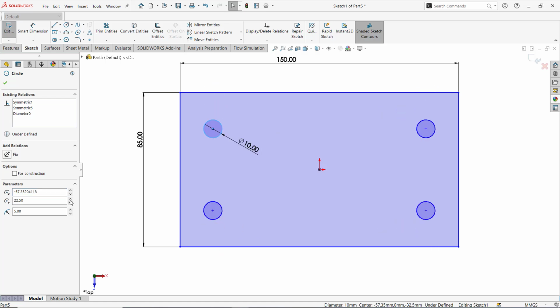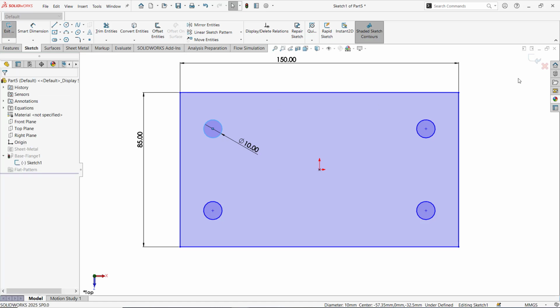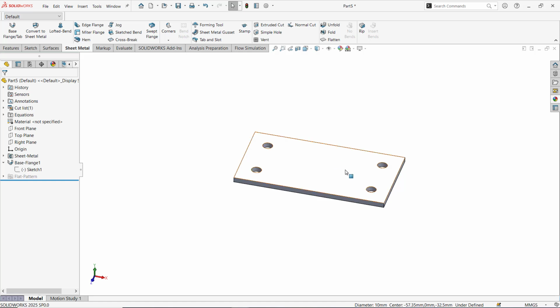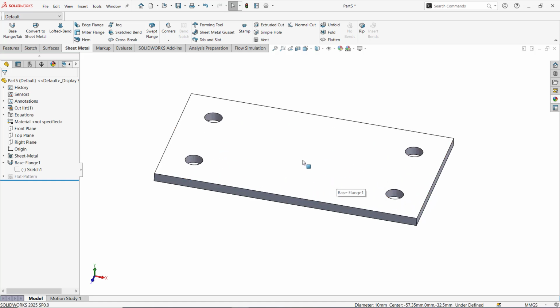When we say choose the plane where the dimensioning is easier, we mean to pick the plane where the main layout of the feature aligns with the plane's axis. The top plane corresponds to the x and y plane. Flat plates usually have the width and depth as their main dimensions. Holes on the plate can be positioned using x and y coordinates directly. This is why the top plane is intuitive for flat plates.